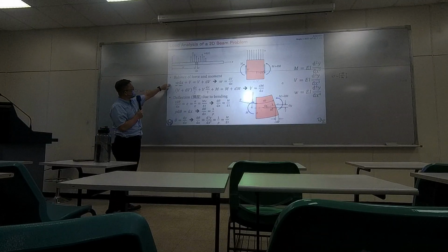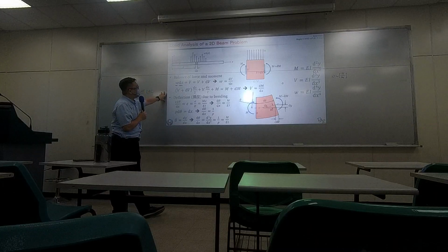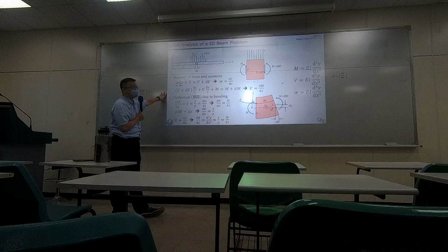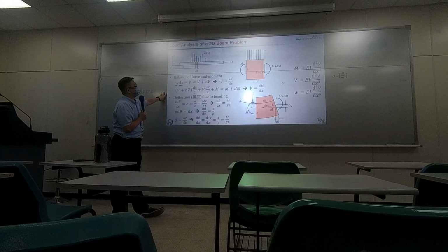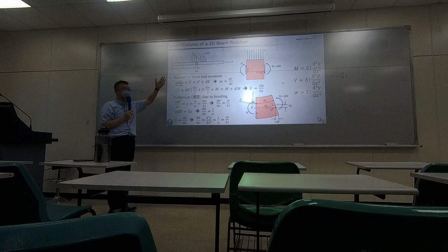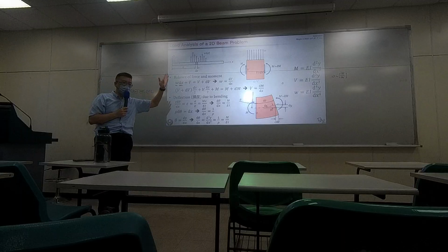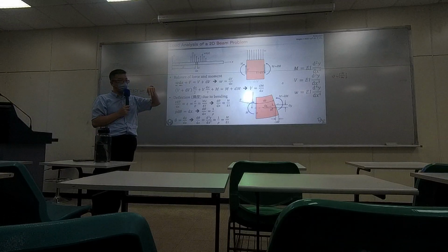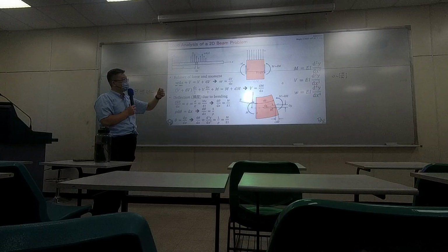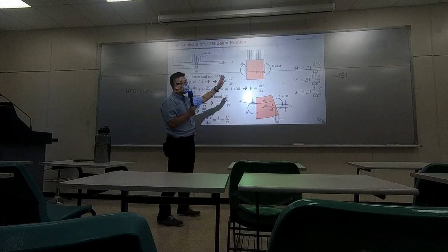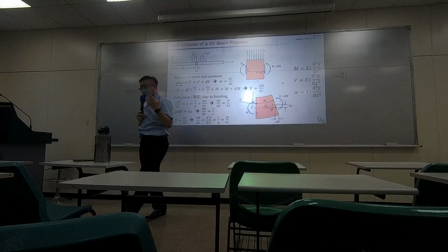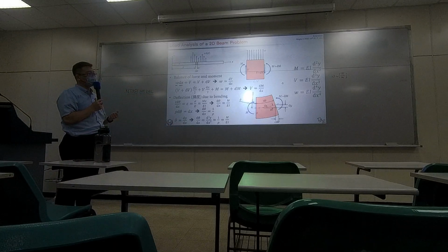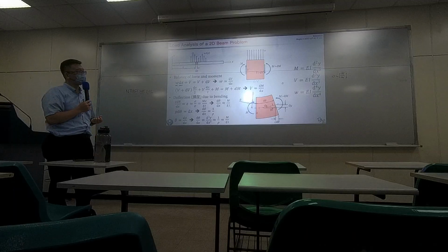Now, basically, the first equation is the balance of force. We need to make some assumptions. Since we have some random loads applied to the beam, and we take a small slice of the beam, on the left-hand side and the right-hand side there could be moment and shearing forces. The only thing is we don't know how large they are.